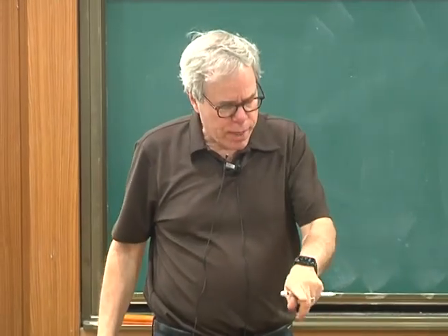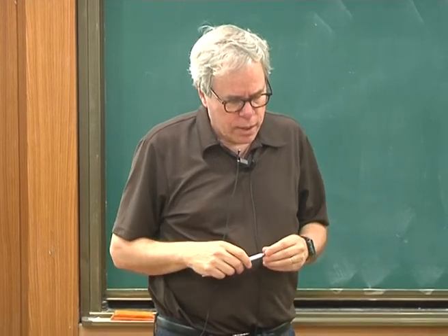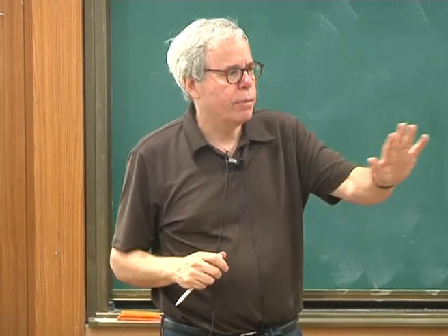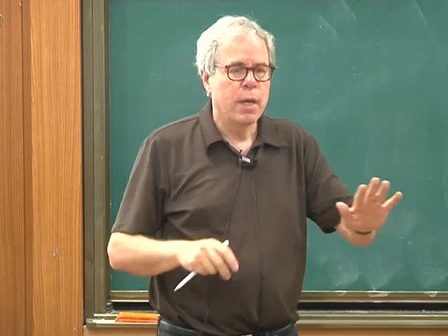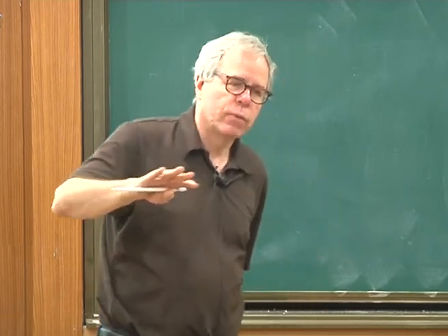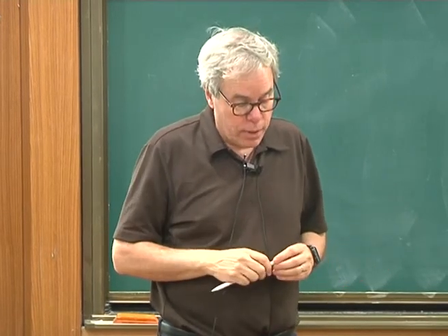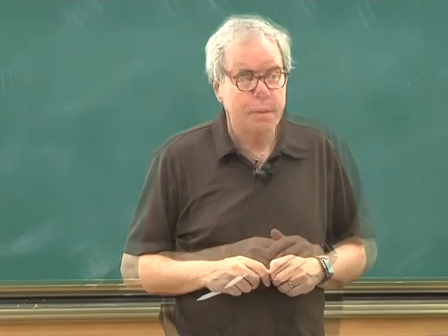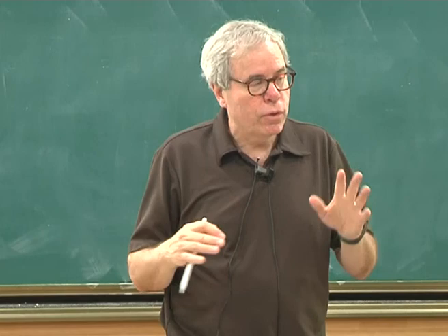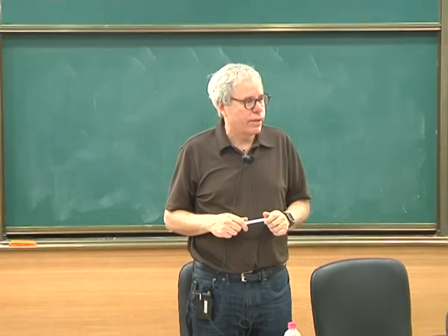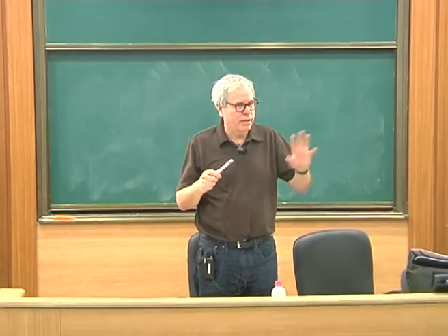And the first paper that did this, you'll see it in the alloy theory community, with some work by Khachaturyan, for example, many years ago. In the solidification community, people didn't try to derive these from first principles. They just put together an indicator function, and some nice work by Wheeler, Boettinger, and McFadden in the solidification community used this idea. But it's basically the same idea. Okay, and there's lots of care in choosing that interpolation function in phi that you have to do in order to get the right answer. So you just can't pluck it out of the air.